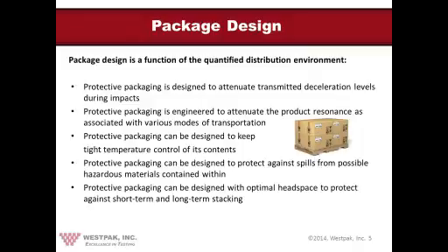As Paul mentioned, if you have a certain kind of product, typically heavier ones, they are closely coupled, if you will, to the vibration vehicle, which means they're stuck there because they weigh a lot. So gravity keeps them on there, and therefore they get the direct input more so of the vibration of the vehicle. Also, larger products can be very vibration sensitive, and our testing has shown that lots of times structural resonance, and that's basically the thing that will kill a larger product, occurs at about the same frequencies where the truck input is the highest. So you've got a kind of a double whammy.